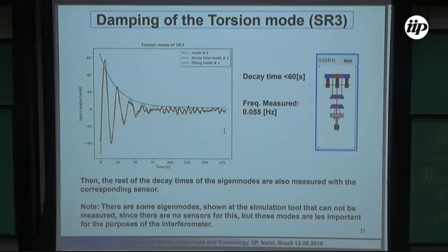Yeah, that's also true, because you cannot isolate this eigenmode from the motion at higher frequencies happening in other parts of your suspension. If another stage of your suspension is also vibrating at a different frequency, it will couple.